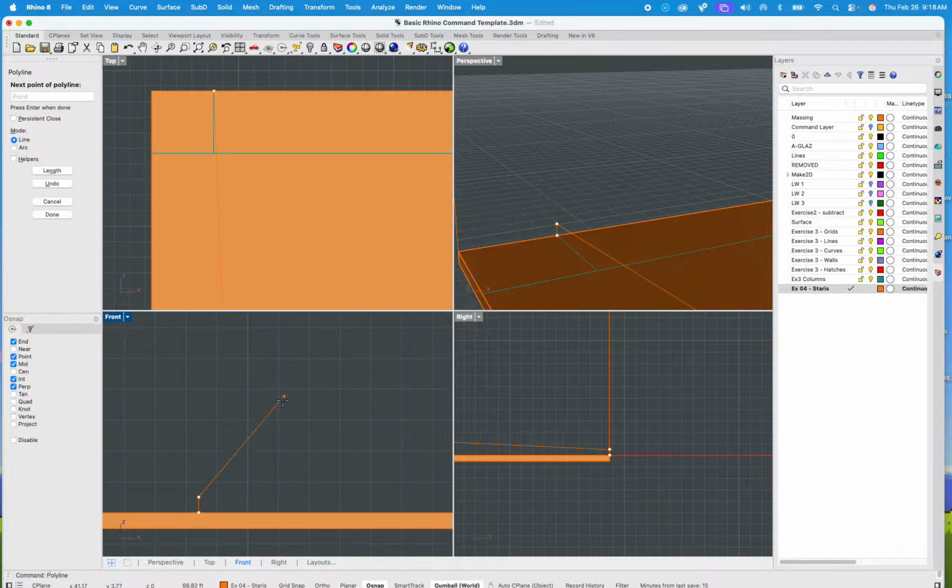So 6 inches, enter. I'm going to hold shift, click. It's going to ask for the next line. Okay, great. In my case, I want to make sure that I go this way. How much do I want to go? 12, thank you. So 12, I'm going to hold shift in this view. That's what's going to cause this. Otherwise, if I don't hold shift, you kind of see what it's doing over there. It's kind of like going this way. But I do want a flat profile.